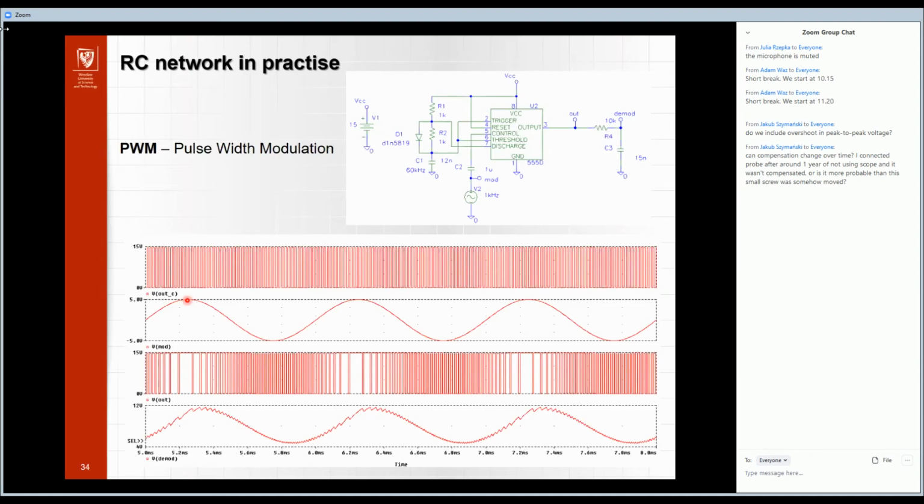For example, we can imagine that the modulating signal is my voice, for example from a microphone, and I must transmit it to the receiver, and so we have such a signal, and using a simple low pass filter, from this PWM modulated signal we can obtain the original information. Of course, it is not exactly the same, but it is very similar, and it is used in practice.